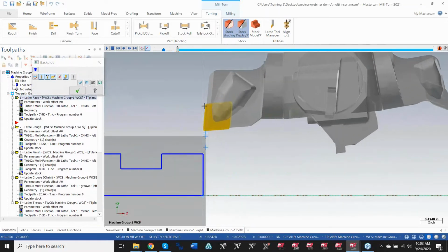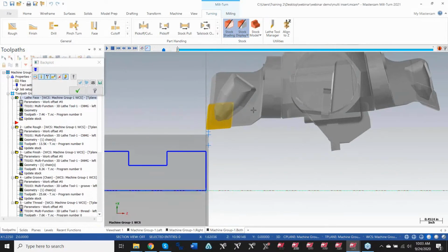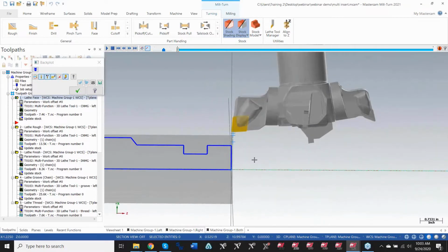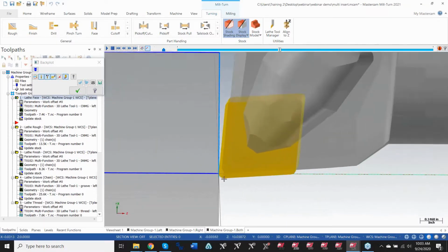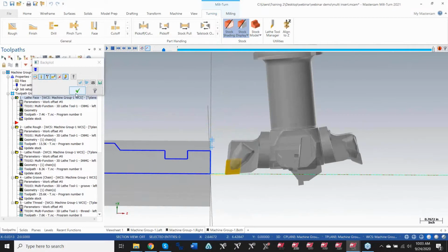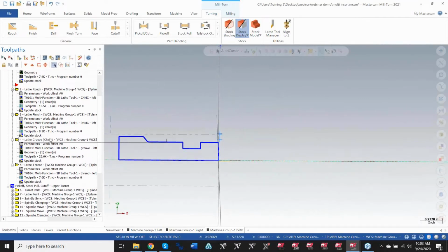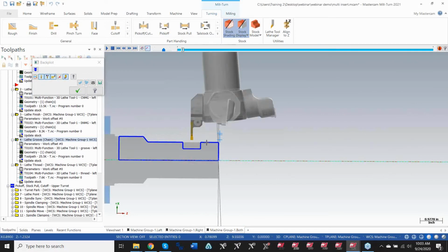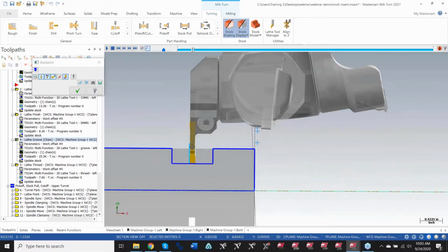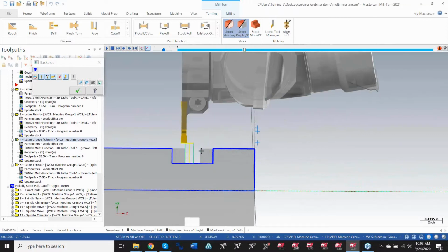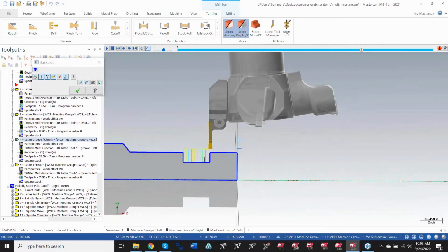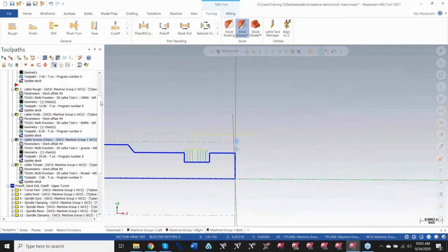It's a 95 degree because you want to make sure that 5 degree or so, they're built off of a tilt. If you look at it, they're all built at a tilt. So you can see right there, nice little face. And then you can see the other tools working in action here, like this grooving toolpath. See, if I just rotated 90, this grooving toolpath wouldn't go in the correct direction. So these are all the same tools.